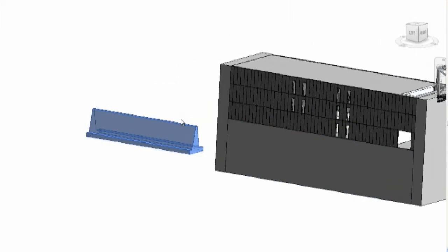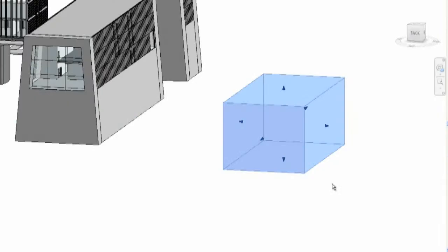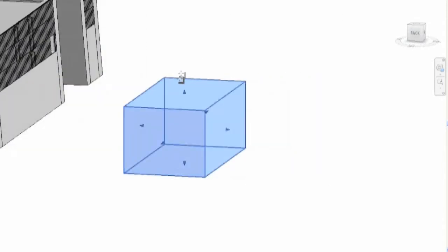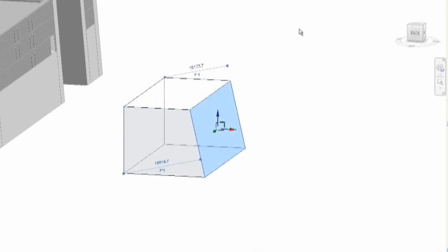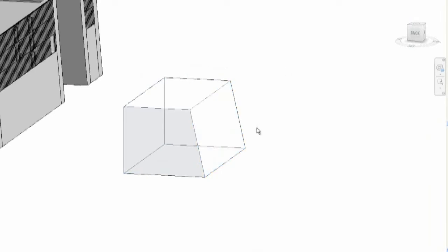During the design process, Ria made the decision to taper the abutment curtain cladding. To build this feature in Revit, she used the In-Place Mass tool, as shown in the example. She then created a mass which was the same dimensions as the main bulk of the abutment. Once the dimensions were correct, she modified the mass so that the elevation tapered inwards as per her design.